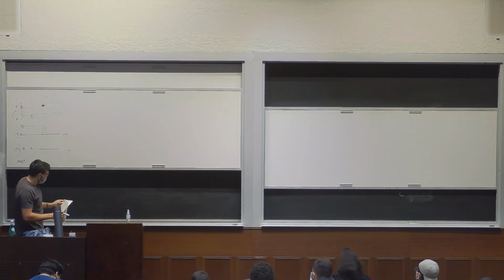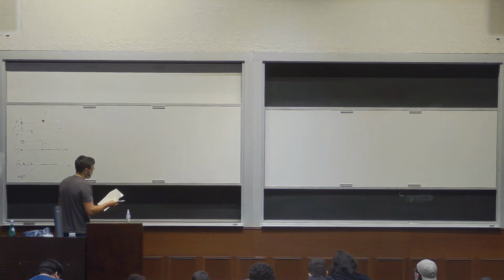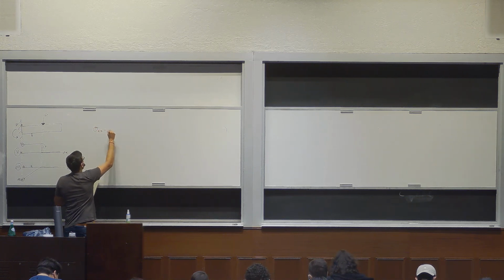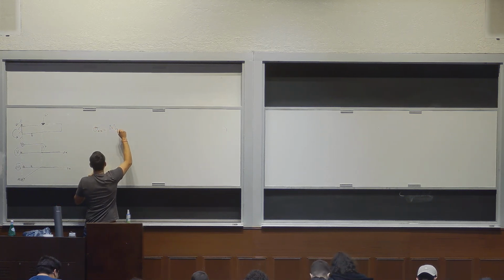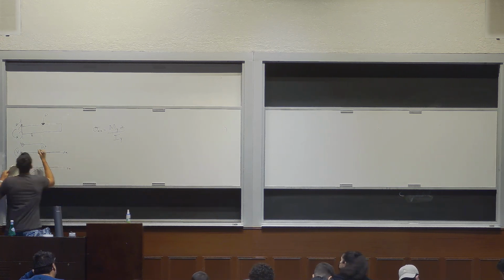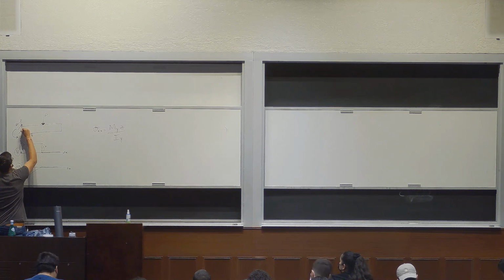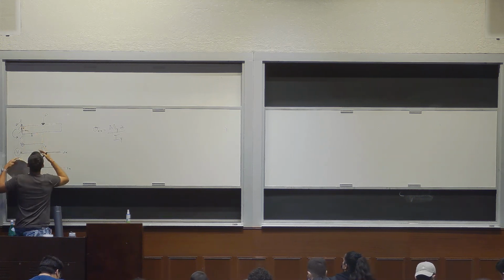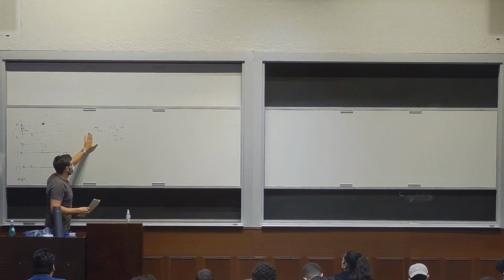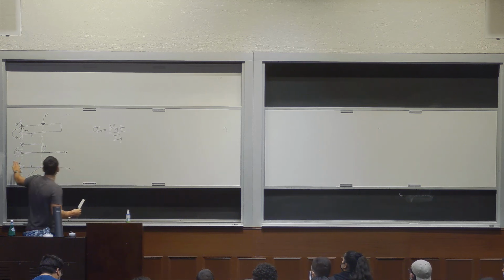All right. So some basic equations that we covered last time, but I'm just going to write them down again. Basic equations for beam bending. So sigma xx equals My times z over Iy. Okay? And that would be in the situation where you have, this is the x direction, this is the z direction, and the y-axis is into the plane, okay? And these are the bending stresses, normal stresses, generated from a moment, M, right?